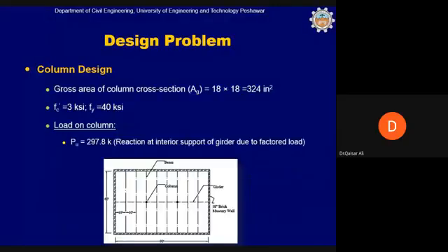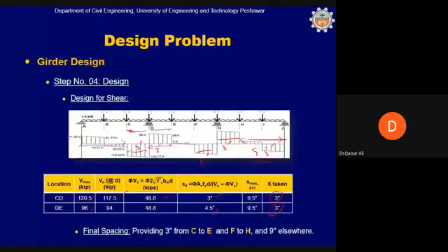We can use the checks. If I had to design this girder in my design office, I would have provided 3 inch spacing from one end to another end, because it's the only girder in this project, and this is one of the most important structural elements. So I will not keep on changing the stirrup spacing, and I will use only one spacing, because in this one girder, if we change the stirrups for economy, we will at the end only save 5 or 6 or 10 stirrups, which in the whole project possess no monetary value. This will not give us a big saving.